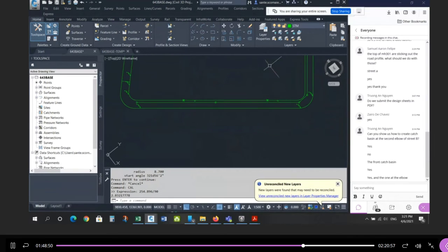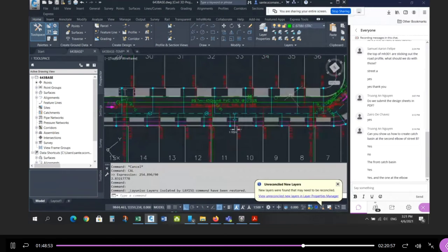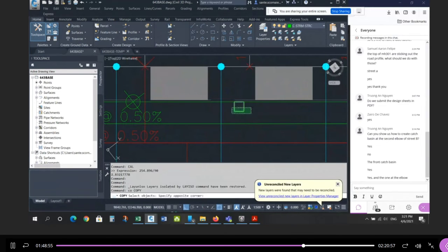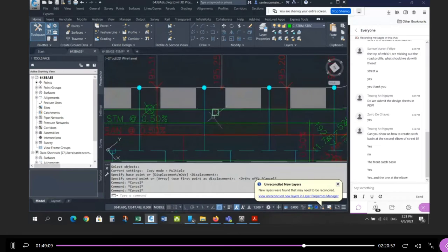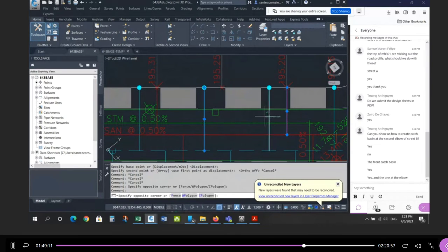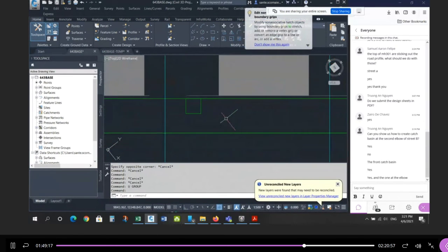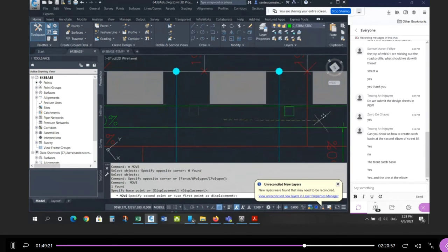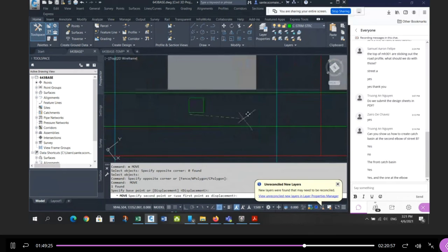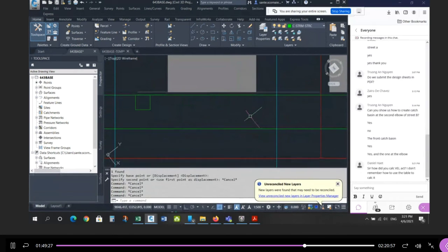Now, when you place the catch basin, once you decide where the catch basin goes and plan based on it, make sure that the catch basin is never on top of a water main pipe or a sanitary pipe, or never inside the driveway. You don't want to drive over this if you can avoid it. So always between sanitary and water, and always between driveways. Okay, whoops. So never put the catch basin on a pipe, water main, on a sanitary water main, or in the driveway.